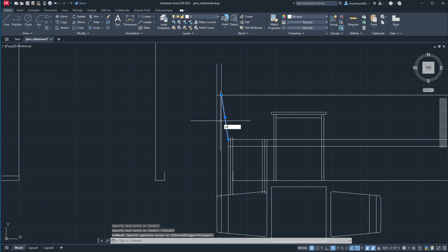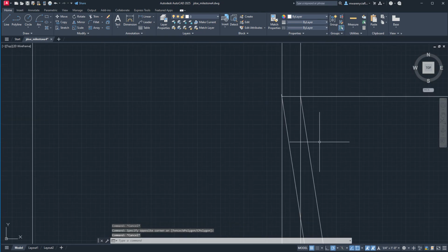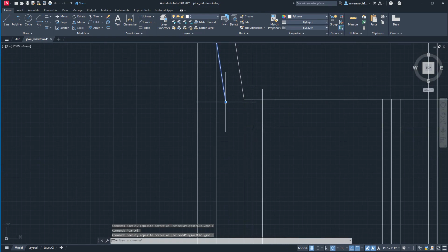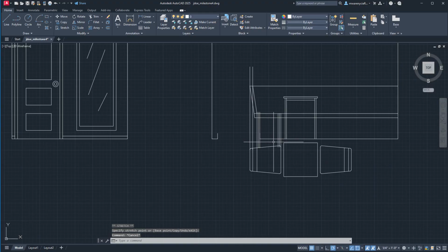And then we'll offset this 2 inches. And I will use this as a reference to finish up the back. If it'll do, there we go. It wasn't doing the extension for me. Okay. So we've got the back of our chair, and then we'll just extend this down to right there. Pull that out. This isn't a perfect chair. It's a good enough chair for a demo.